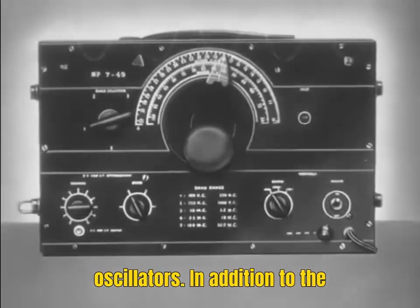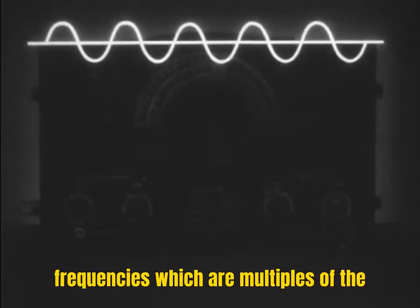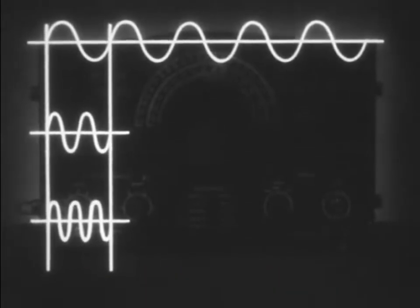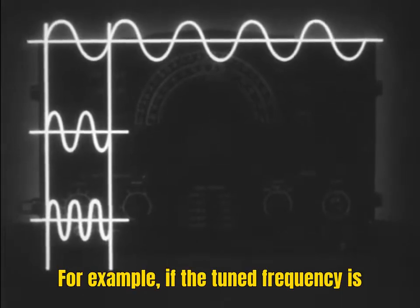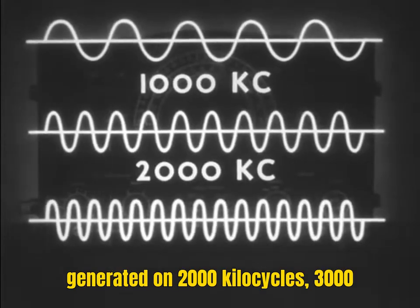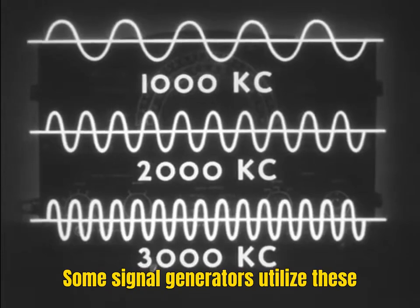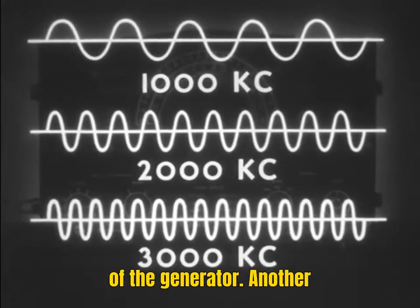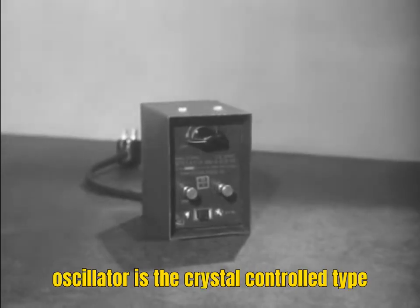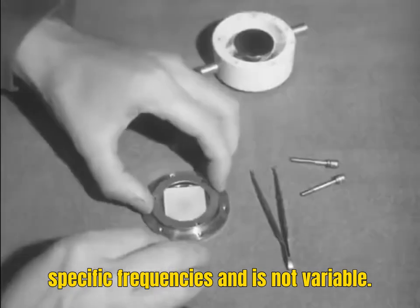In addition to the fundamental frequency generated by an oscillator, it may also produce several frequencies which are multiples of the fundamental, although weaker. For example, if the tuned frequency is 1,000 kilocycles, a weaker signal may be generated on 2,000 kilocycles, 3,000 kilocycles, and so on. Some signal generators utilize these harmonic frequencies to extend the range of the generator. Another oscillator is the crystal-controlled type, designed to operate on one or more specific frequencies and is not variable.